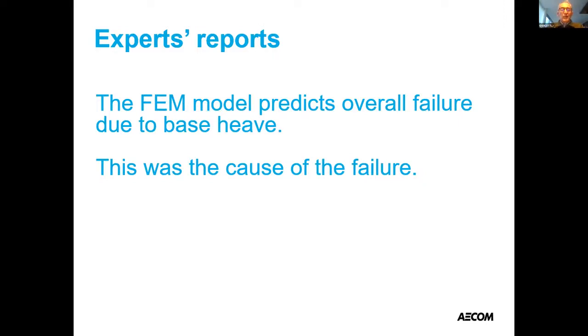There were many experts called into the inquiry because there were so many parties involved. There was the main contractor, two subcontractors, permanent works designer, temporary works designer, checker, insurers. And each of these persons was represented at the inquiry and put forward experts who gave opinions that might be useful to guide the court of inquiry. And 3 experts reported that they had analyzed the collapse using finite element models, and they said that the model predicts overall failure due to base heave.